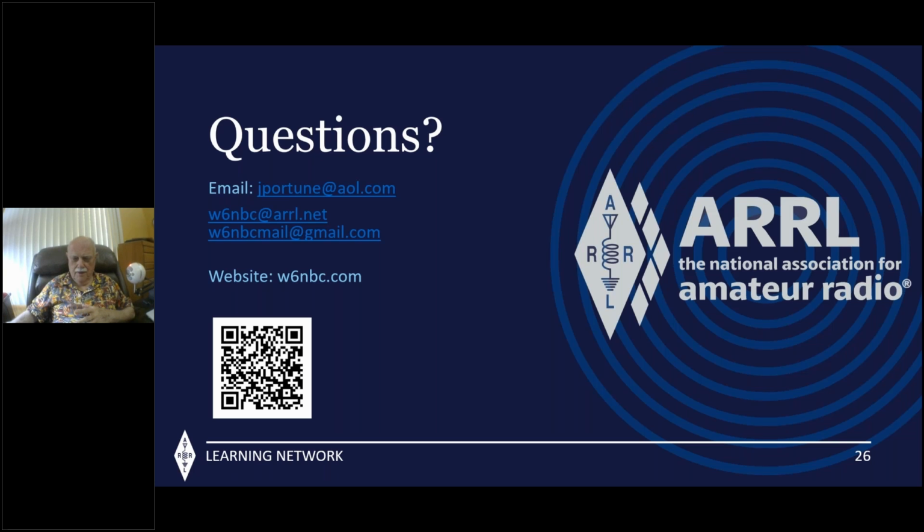Our first question: my 6-meter 3-element Yagi has a T-match, part of which is a Balun. Is a choke Balun at the feed point recommended? Well, if you've got a Balun up there already as part of some other device, you shouldn't need one.